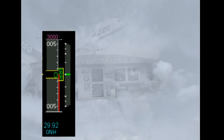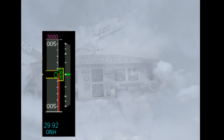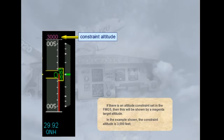The aircraft is on the ground just prior to takeoff. Notice that with a QNH of 29.92, the altitude indication is 10 feet. If there is an altitude constraint set in the FMGS, then this will be shown by a magenta target altitude. In the example shown, the constraint altitude is 3,000 feet.